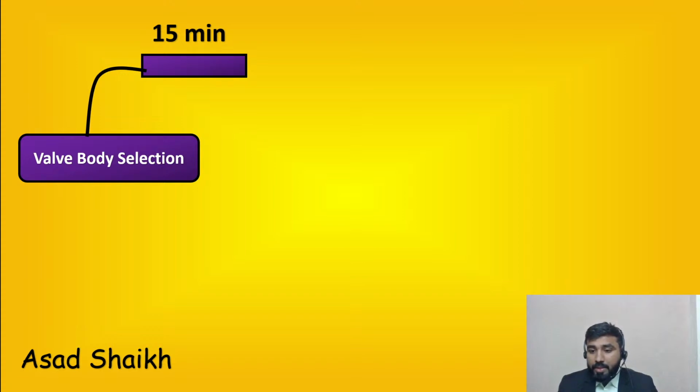Okay, I see. Selection, points to check in TBE. Selection, choked flow, trim and selection of the types of trim which are available. If cavitation occurs, what will be the suggestion by the engineer to rectify? Fugitive emission type testing.